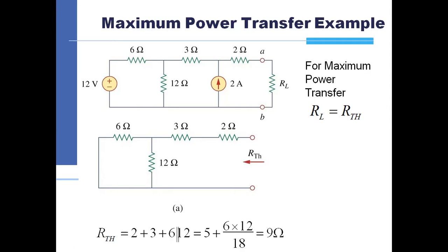So here, when we are supposed to calculate the value of the Thevenin equivalent, you can see, if we take this 2 ampere source as an open circuit, then this node will not remain, because only two components will remain. This will be in series. If these 2 and 3 are in series, we can calculate them: 2 plus 3 will be 5 ohm. Again, to calculate the Thevenin equivalent resistance, we can see 2 and 3 plus 2 and 3 are in series, so you will get 5.